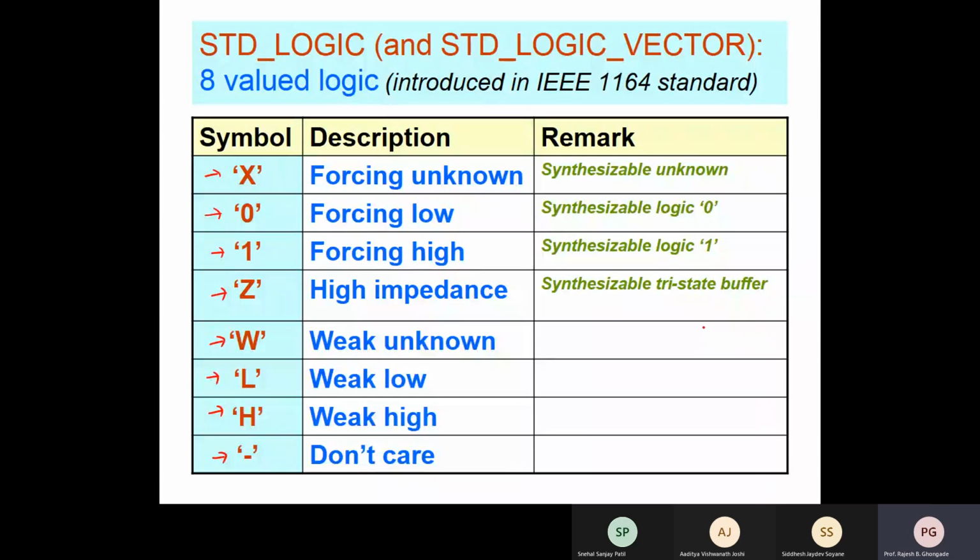Okay. For example, if you are having an AND gate, so what you are doing here is when you are connecting 0, or let us say connecting 1 here, what are you actually doing? You are actually forcing the voltage here, making this 0. In this case, you are forcing it to be, if it is TTL, somewhere around 4.5 to 5 volts. So the concept here is that your assignment is in terms of forcing the voltage. Okay, that is the reason why it is called forcing.